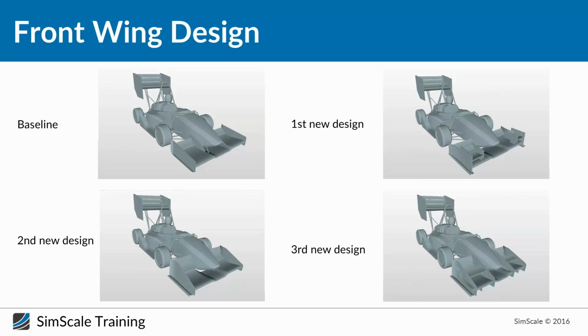Yeah, that's right. So let me give you a quick idea about what we did in this design. First of all, we have redesigned the end plate completely, and we have introduced this concept of the foot plate on the end plate. The idea is, guys, you know that vortices are created when the air tries to move from a high pressure region to a low pressure region.